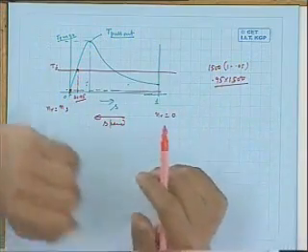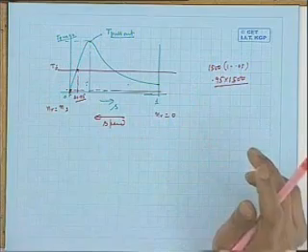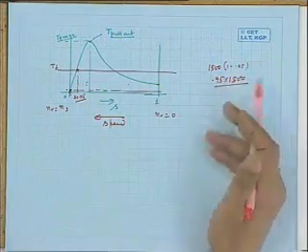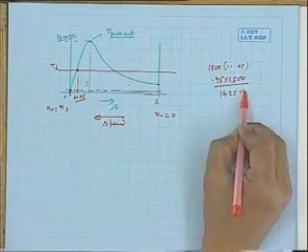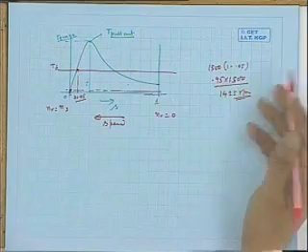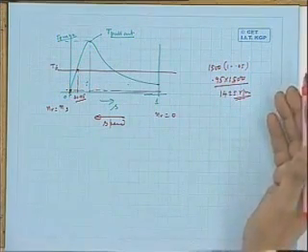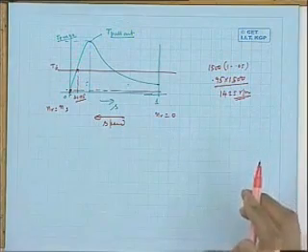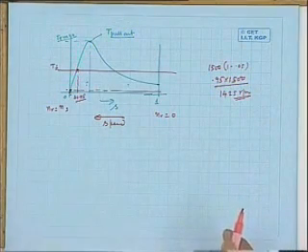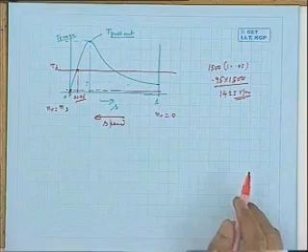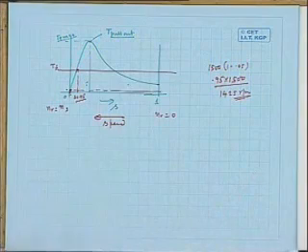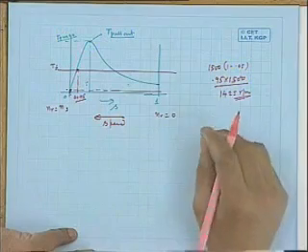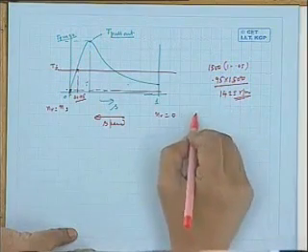So what I want to tell is, the variation of speed of an induction motor from no load to full load condition is not very large. It was running at 1500 rpm. How much does it come to? 1425 rpm. So only 75 rpm has changed on a scale of 1500 rpm. So the speed variation of an induction motor from no load to the full load condition is very small. That's why induction motors are sometimes called constant speed motors.